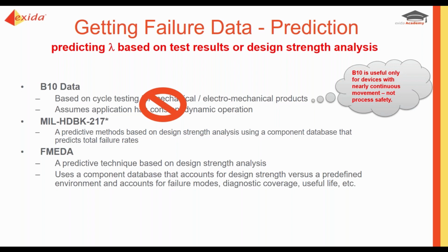The FMEDA takes into consideration the application, the environment, the service, and it accounts for the failure mode, the diagnostic coverage, and the useful life. So because the FMEDA is more up-to-date than the 217, I'm going to dive into that a little bit further to explain how you get failure rates from that technique.